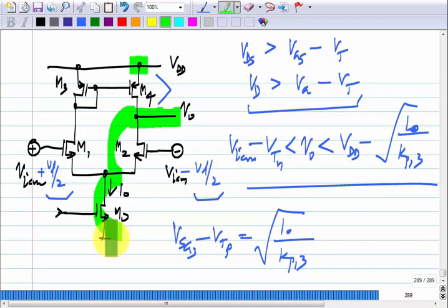Yeah, that is correct. So, that is the reason why in that case we do not... I mean, if you have a multi-stage op amp, it is the input common mode swing of this that is relevant. The output swing is not relevant because it is not going to swing much. It is the output of that stage that will limit. That is correct. So, it becomes even less critical. Any other questions?